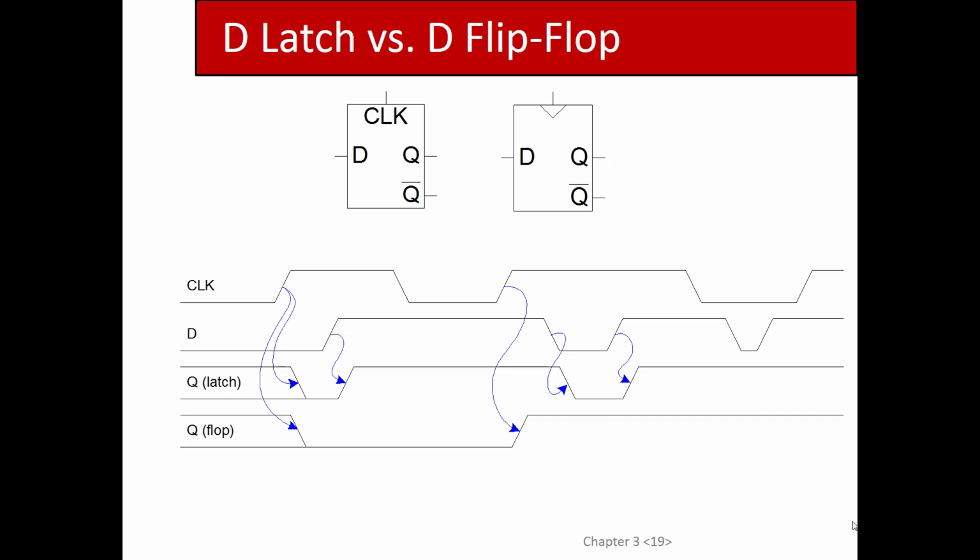Now notice what they did here. You see this double line that they put here? The reason they did that is because they didn't know how the flip-flop was going to be initialized. So the flip-flop might have started out at 0. If it did, then actually Q wouldn't have changed at all. But if the flip-flop was a 1 before this timing diagram began, then we'll see a drop in Q after that first rising edge. You guys with me? So it's kind of ambiguous what it was, but we know that after the clock it's going to be 0, right?